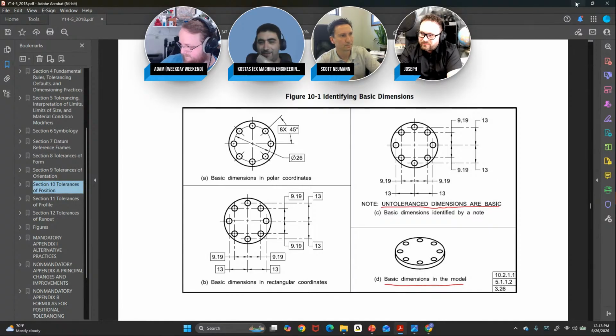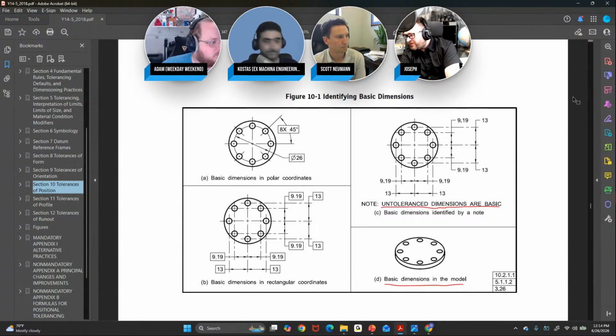And can I just say for our Libre users that if you make a single hole and then do a circular pattern of it, you will automatically get the bolt circle showing in your drawing. That's just a CAD use thing, if you're so inclined. Whereas if you pop in the individual holes, you can still draw the bolt circle, but you won't get it automatically. Yep. Good opinion question on this one, I think.